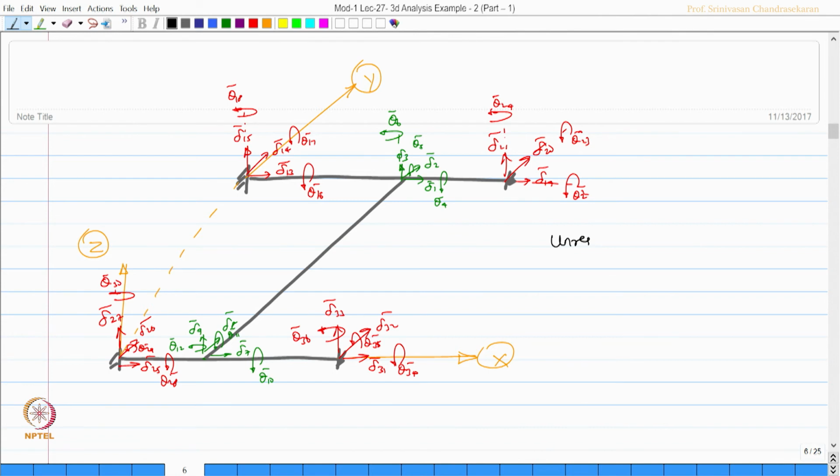So, there are unrestrained degrees of freedom, which is varying from labels of 1 through 12, and restrained degrees the labels are varying from 13 till 36. Okay. There are 6 joints, total 36 degrees of freedom, out of which 12 are unrestrained, remaining all are restrained degrees of freedom. So, now having understood this, let us mark the labels. The labels of the member E B, because this is A, this is B, this is C, D, E and F. So, we are looking for this member because this member is actually loaded, is it not?